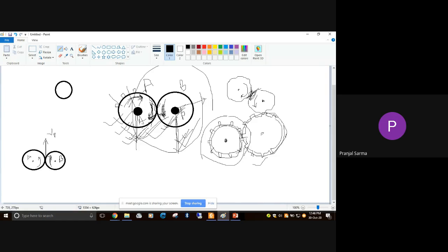In that particular case, why are we talking with respect to shaft position? Because the importance is that we want the motion here on the shaft. The shaft is rotating, and why is the shaft rotating? With the help of these gears, because we are mounting gears here. We key the gear to the shaft, so that whatever is the velocity of rotation of this particular shaft, we get the same velocity of rotation on the gear which is mounted on this shaft.